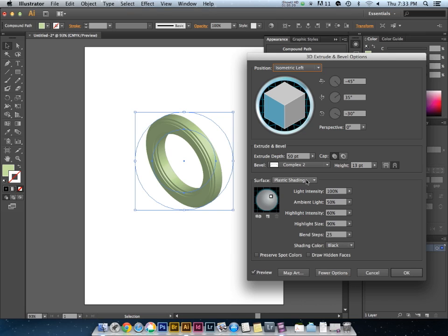So it's not perspective. Remember, perspective, everything tapers to a vanishing point. In isometric, all the lines are parallel. So if I extruded this infinitely deep, the lines would not taper in the distance, they would stay parallel in the distance. That's basically what isometric is, a real rudimentary definition.